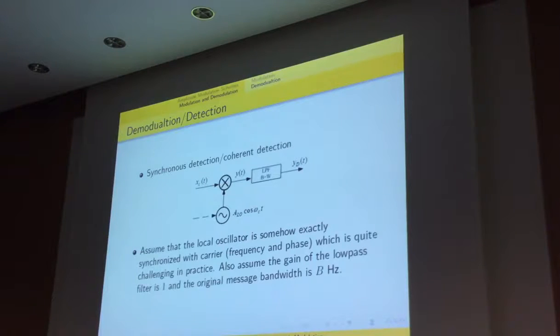Okay, there are two independent oscillators. Somehow, by signal processing technology, we can achieve this such that the receiver side local oscillator has the same frequency and same phase as the transmitter oscillator. Since the transmitter and receiver are far apart, how to achieve this is itself a very challenging task. Even today, in research, this is not achieved perfectly. More or less, they still have some residual errors.